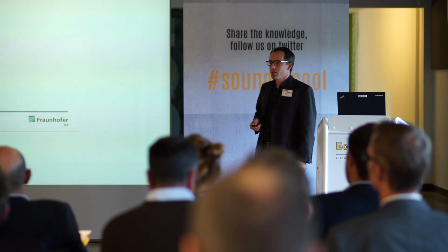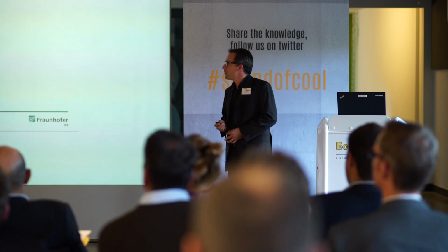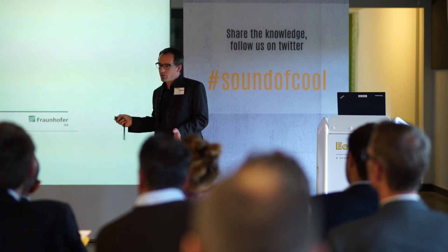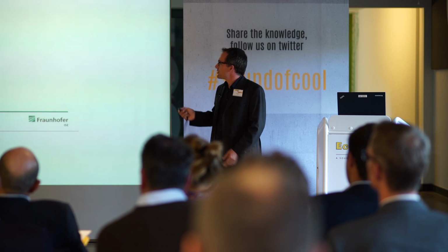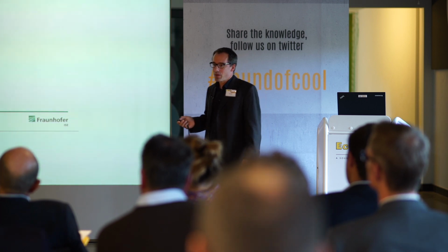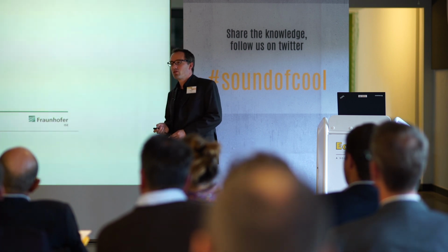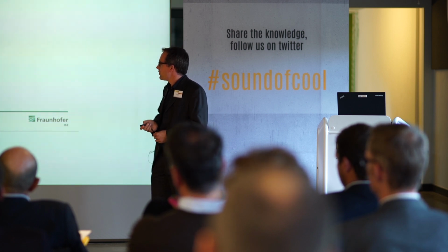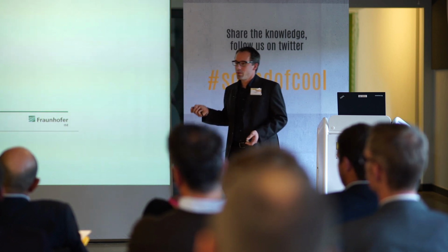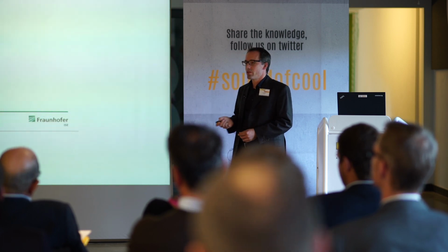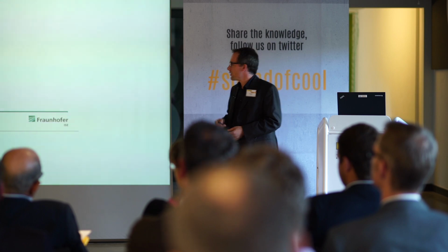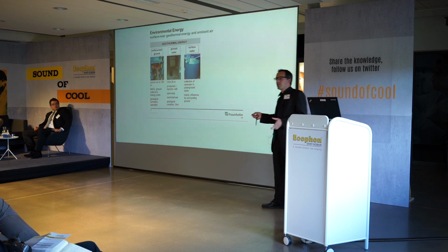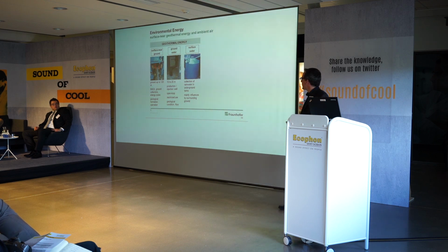And what about the sources we're trying to access? One typical source in the environment is geothermal energy, that might be surface near ground by using borehole heat exchangers. That can be groundwater, if it's applicable. So there might be restricted use if you are allowed in that area to extract water from the ground and reject it again. But that can also be rainwater collected in large tanks and then buried into the ground.